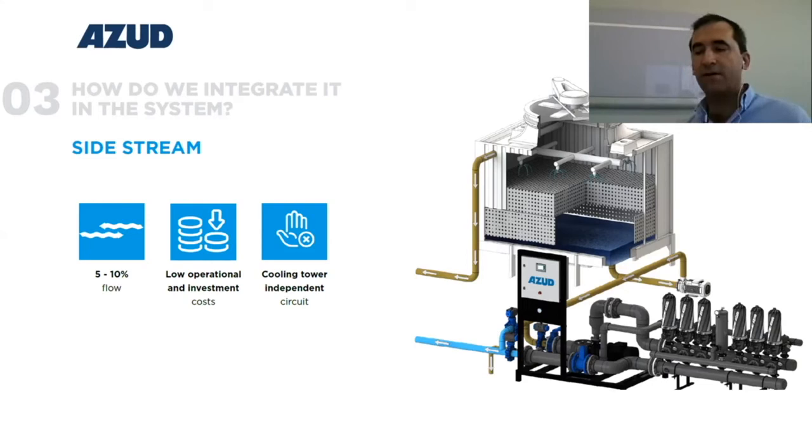Second, you have a reduction in energy consumption, as side stream filtration reduces the likelihood of scale and fouling on the heat exchanger surfaces. Even the smallest layer of scale or fouling on the heat exchange surfaces can reduce the heat exchange rate, forcing the system to work harder to achieve the desired cooling and in turn increasing energy costs.